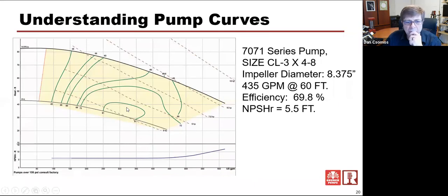let's say we're running 7 amps, which is roughly about 8 horsepower, okay? So 8 horsepower, we know should be somewhere right in this range right here, unless there's something strange going on. So if we know that we're running about 8 horsepower, but we're not matching with this impeller, we're not matching this pressure, and if we have some kind of a flow meter on this thing, if it's not matching that general area, give or take a few percent, 5–10%, then something else is going on.